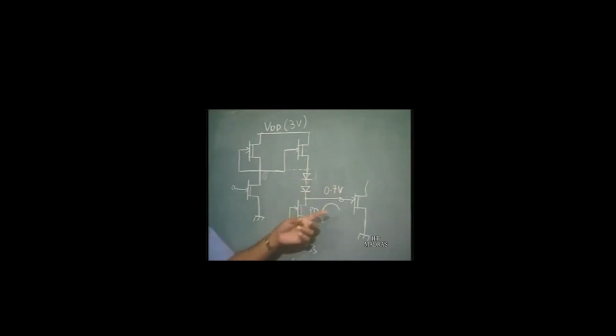So, here there is no clash of currents. This pull down transistor is on, the source follower is off, and the full current of the pull down is used to switch off the output transistor. On the other hand, suppose this voltage is negative, say minus 1 volt, that is less than the threshold voltage. So, this transistor is off.